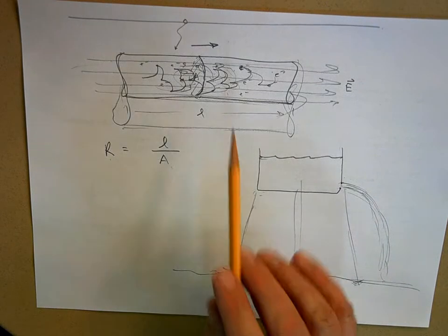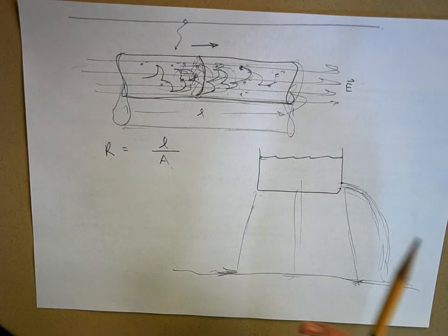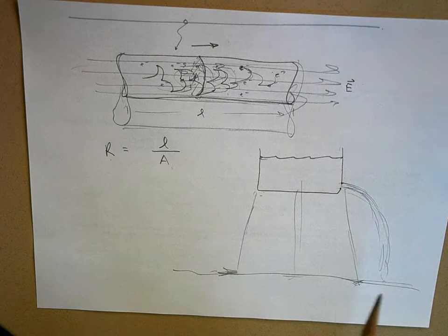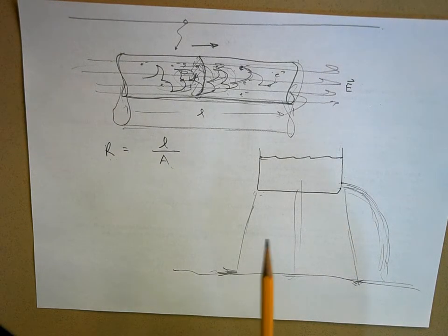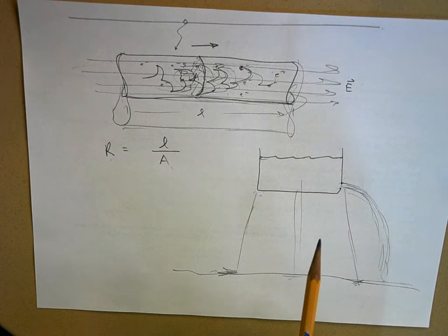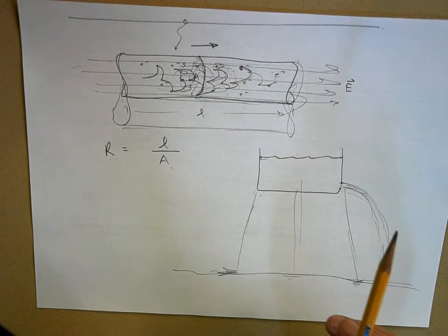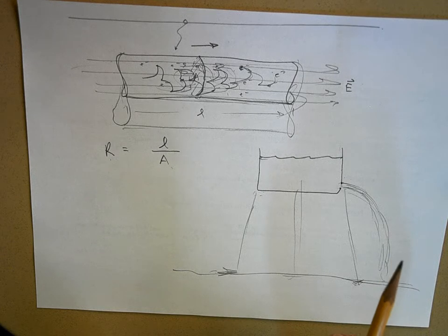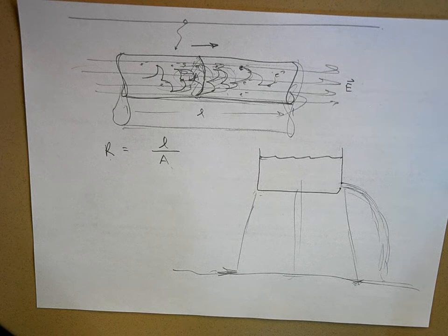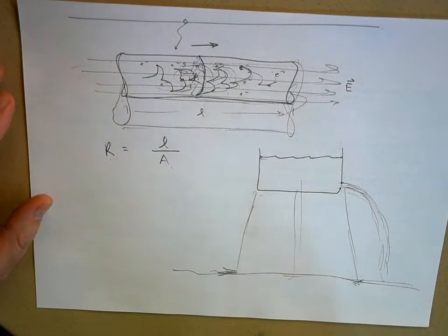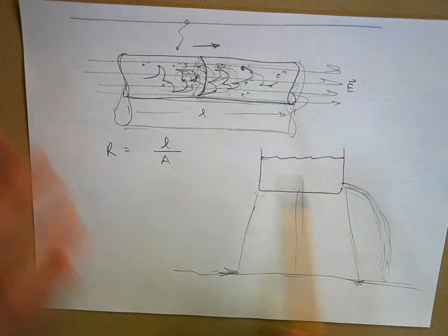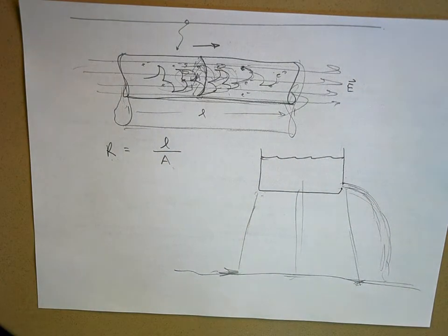Same is true with a wire. If you make the wire thicker, it's easier for the electricity to flow through it, and it'll reduce the resistance of that wire. Now, those of you on the robotics team know that if you're going to have a lot of current, you have to have a certain gauge of wire to match that current. The thicker the wire, the more current you can put through it without it getting hot. So that's what's happening here. Now, think about it. In terms of the resistance of a long length of wire, that's pretty much all I can change, right? I can change the length of the wire and I can change the thickness of the wire.